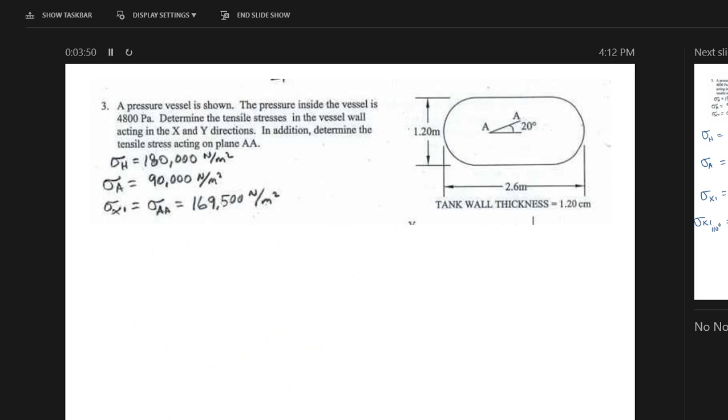If you want to find the stress, what angle are you going to use for that one? 20 plus 90. Yeah, 110. Okay, I was thinking of strain. Yeah, I know, that's why I'm bringing it up, because there's so many of these different relationships. So when you're doing stress, you reference to the vertical plane, right? That's what you do when you're doing stress. I didn't draw that quite vertical, but you get the idea. So that'd be 110.